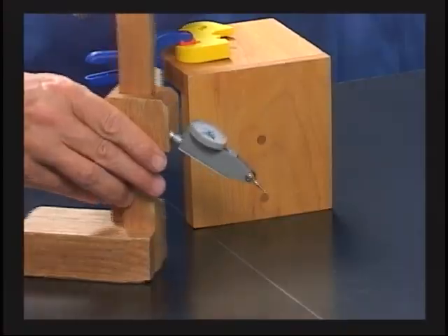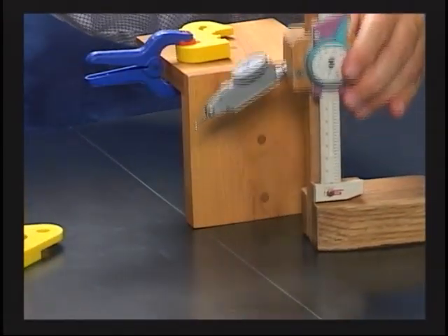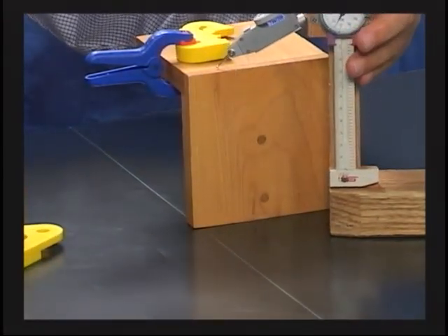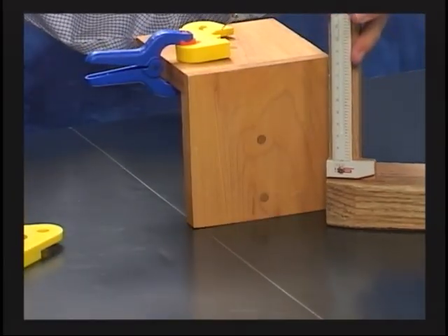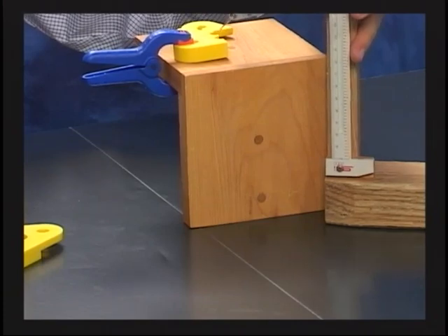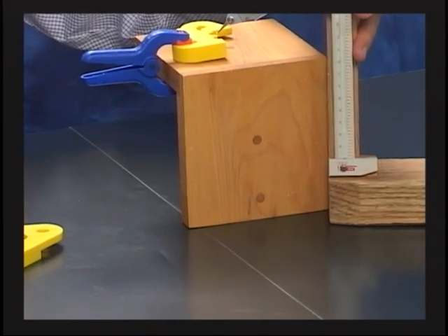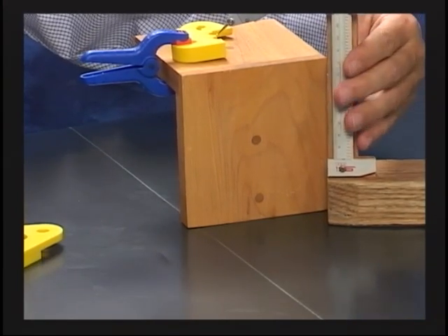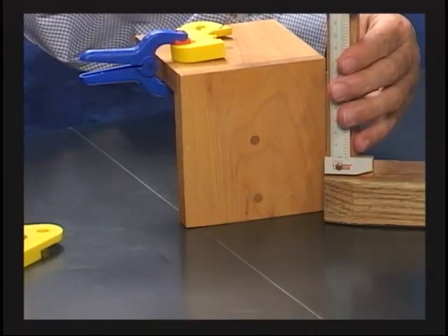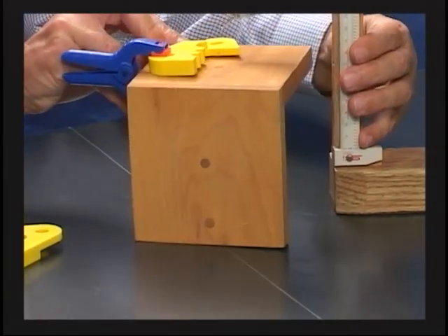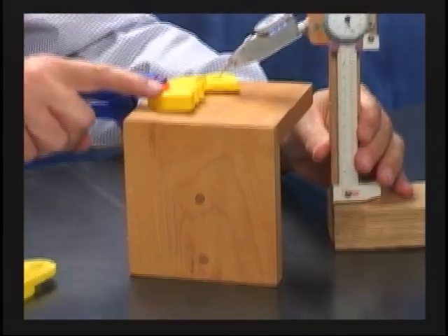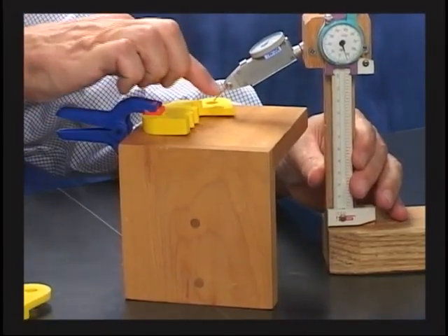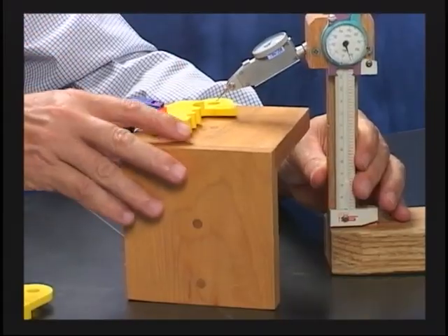You see with my height gauge here, I set it up. I can get my 0 off the plate. Remember all those dimensions? Remember where we were checking this surface here? I think that surface had to be within 500, not a plus or minus, but a profile of 4. Then we came over to this surface, and we were indicating this surface. That had to be within a zone. See, what I'm doing is resting on the high points. I'm coming to see if that falls inside of the tolerance zone.